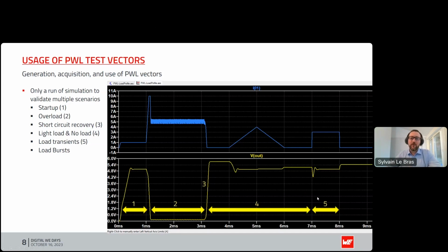And then we get to the most typical testing that we often see in datasheets and application notes. It's called the load transient, section 5. The load transient in section 5 is just stressing the output of a converter, testing both its ability to regulate, to answer fast, and not to have overshoots and oscillations in its response. What we can see here is that going from 0 amps to 3 amps just creates a little dent in our output voltage, another shot, and then it stabilizes. I would consider that this kind of answer of the DC-DC voltage is okay for me.